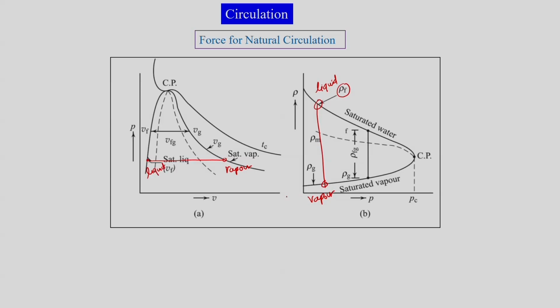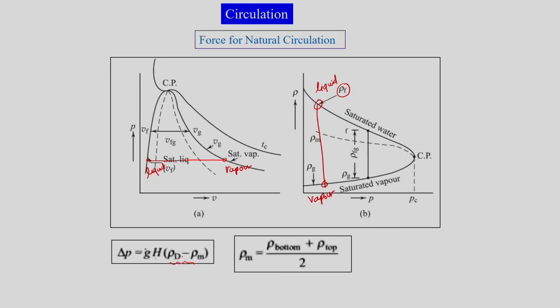So, we get at lower pressure a large density difference to help the natural circulation of water inside the said loop. Here the necessary buoyancy force for the circulation is based upon the density difference and the head provided by the circulation tubes. But here we need two densities.